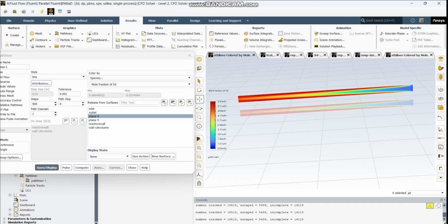This distribution clearly shows the effectiveness of the catalysts and the thermal gradient in promoting the reaction. Factors such as surface to volume ratio, reactor temperature distribution, and pressure significantly impact the yield. The current surface to volume ratio provides an adequate catalytic surface area to support the reaction, but enhancing it further may improve the conversion.